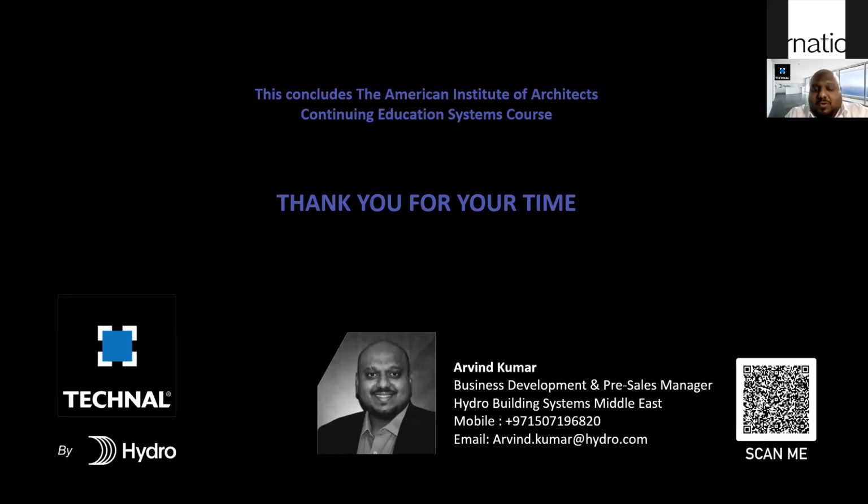See, when it comes to using tested systems, for example Technal, you don't have to go and test again. If you don't change the facade format, the mullion depths, and if you follow exactly from the book, you don't have to test again. However, as you start modifying the system, where you use different elements which are not representative of the earlier tested system, that's when you go for project-specific testing.